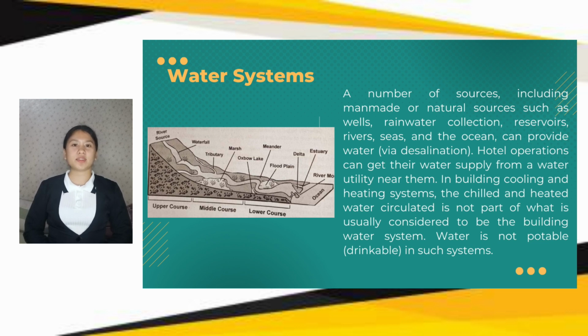A hotel establishment needs a lot of water for various essential functions. An average figure is 200 liters per person per day. Cold water is used for diverse functions in a hotel, like drinking, cooking in the kitchen and restaurant, laboratory wash sinks and wash basins, laboratory flush, laundry, estate and floor cleaning purposes, fire sprinkler systems, cooling the diesel generating set, refrigerator plant, etc. Hot water and boiler make-up water, gardening, etc., and in swimming pools and other water bodies, if any.